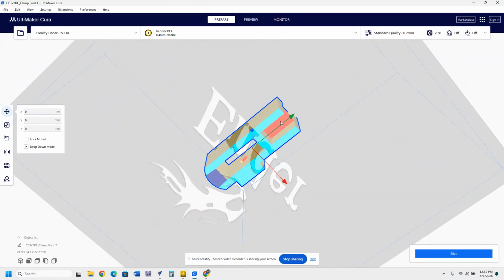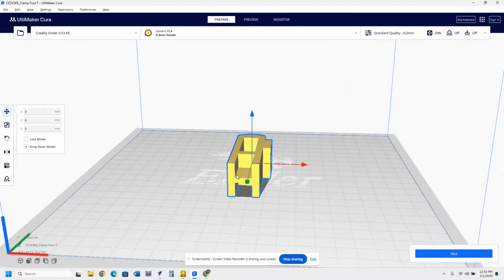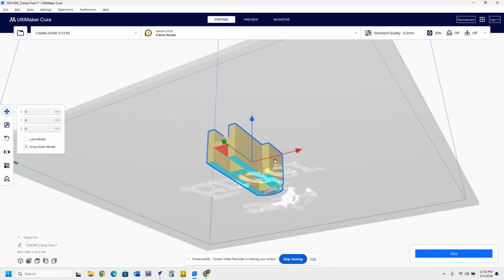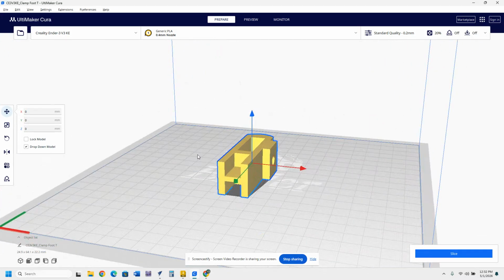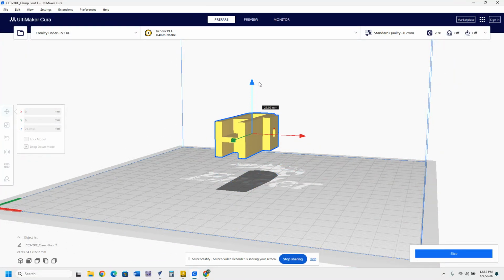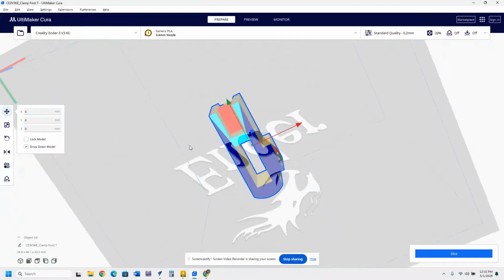And you can see there's a red section here, but that's okay, because if we look at this from this view, that red section is a part that's hovering above the surface. So of course, naturally that would be red. You can also see there's a little red here as well. Those are okay. Now I'm just going to check it by grabbing the blue arrow. I'm going to bring it up and let go. Left mouse button, release, and yeah, we got a lot more dark blue now.